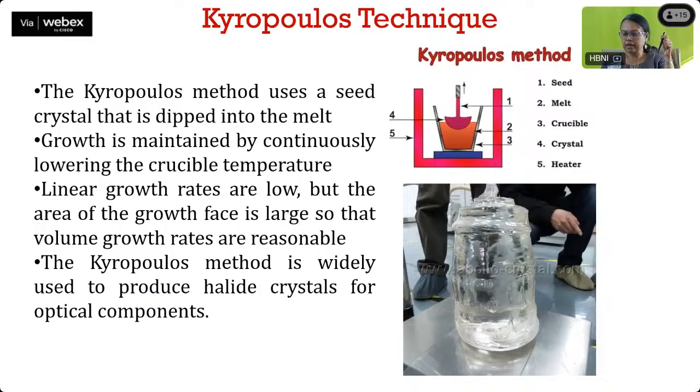So in the case of the Czochralski-type seeded method, what we are doing is growing like that. We are just dipping the seed into the melt, and we are not pulling or lowering, we are just letting it remain there and slowly decreasing the temperature so that with the seed the whole crystal grows. The method uses a seed crystal that is dipped into the melt.